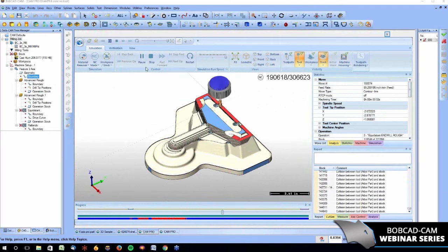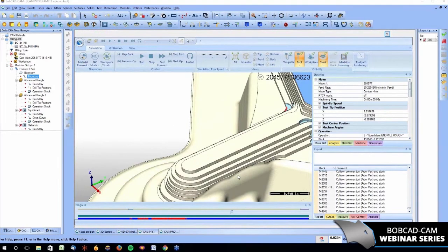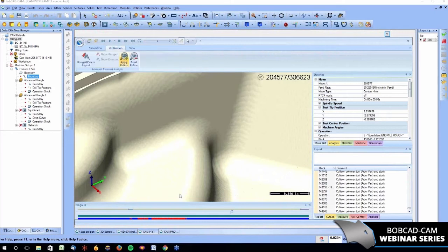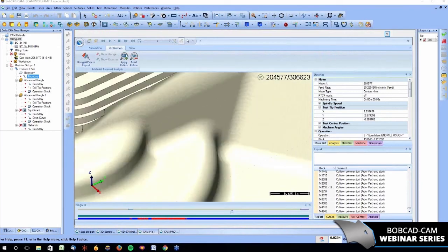Okay. So if I just pause it, because we're going to have to come back in here anyways to make the adjustments here, but we're going to fix a few things so you guys can see it. We look at the surface. You guys will be able to actually zoom in. You guys can go over to the actual refining options, okay? Under the actual view, or verification, you have apply refine. What it does is it actually focuses your graphics card into that certain area that you've zoomed in on. So when you zoom in, you hit apply refine, and what it does, it focuses all your graphic intention so you guys can actually see scallops better. You know, that way you're actually seeing what's going on and stuff like that, okay?